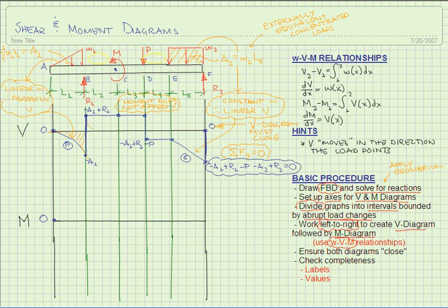We need the area of all of these various shapes on our shear curve. So one thing that I typically do when I'm working on my shear and moment diagrams is, before I even dive into my moment diagram, I'll just calculate all of these areas. So we'll just call this area 3, area 4, area 5, area 6. Since this piece here is a composite shape, we'll break that up into actually 2 areas, a triangular section and a rectangular section. This piece here may be a shape unfamiliar to some of you. If you look on your RDC, your reference data card for CE300, that's a parabolic spandrel.